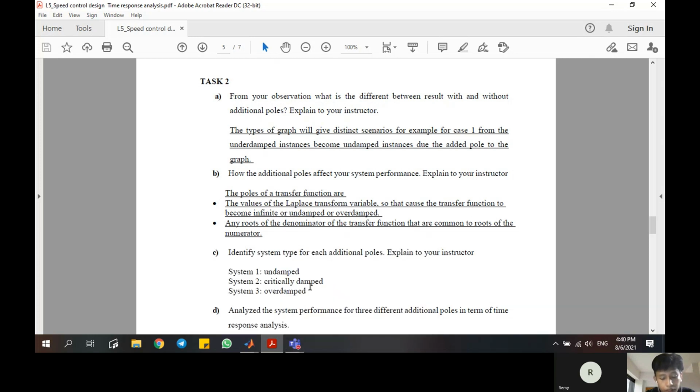And system 3 is an overdamped system. The overdamped system response is a very slow response used when bringing a system up to temperature. For example, when a process cooker is first brought up to heat, it will be heated slowly so that it does not crack. The heat from the cooker comes from steam. The steam valve is controlled with an overdamped response, so it opens slowly and allows the temperature to increase slowly. It may take over an hour to bring the temperature from room temperature to 200 Fahrenheit.